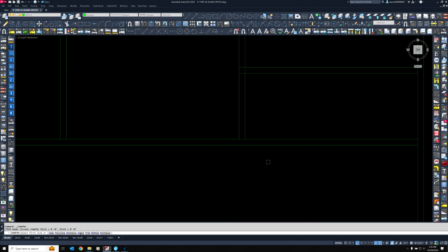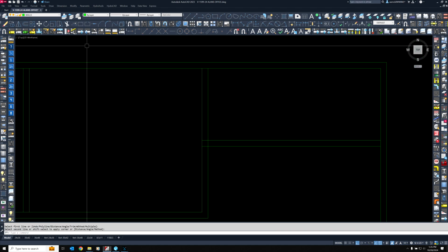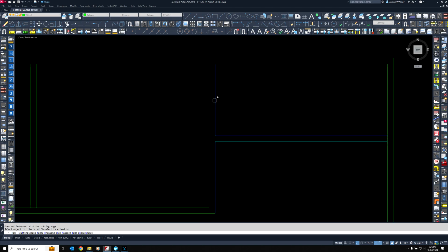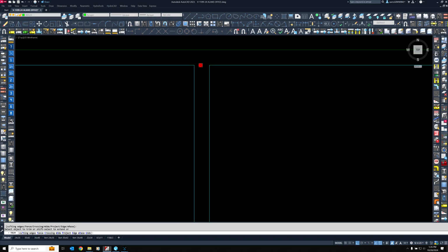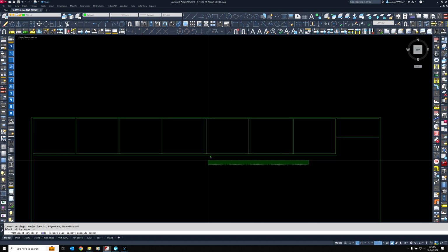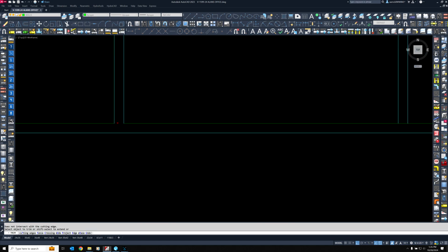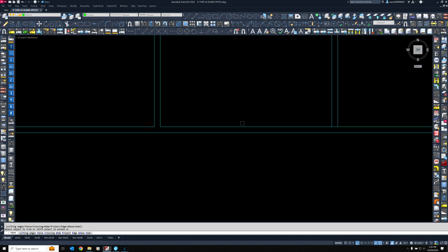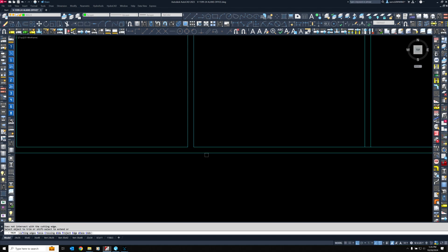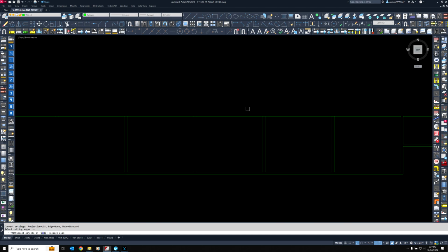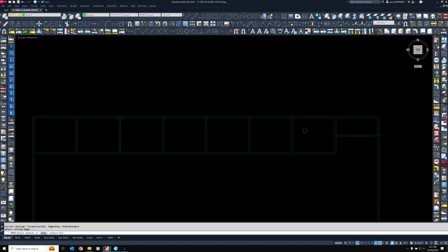Let's chamfer, and then let's trim. We want to get rid of all these lines that are not broken. We don't want them to look this way for more than one reason. So if I hit the scissor button, I'm in the command ready to select my objects.